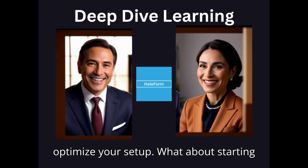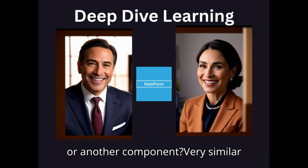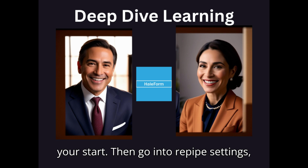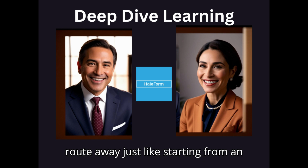What about starting a purchase length pipe right off a nozzle or another component? Very similar process. Select route pipe, click the nozzle or component connection point as your start, then go into route pipe settings, set use purchase length how you want it, and route away just like starting from an open point.